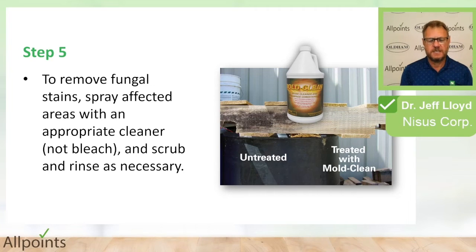If you've already got significant mold problems, if all of those studs are black and you can visibly see that, we would recommend treatment with a product such as Mold Clean, which will remove that fungal staining and remove that surface mycelial growth. You apply that product. You can physically scrub the surfaces. If the home is still really wet and flooded, you can even pressure wash in certain situations, although typically I don't recommend that. A very stiff brush, brushing that after application, and then a rinse off will normally do a very good job of cleaning that material.